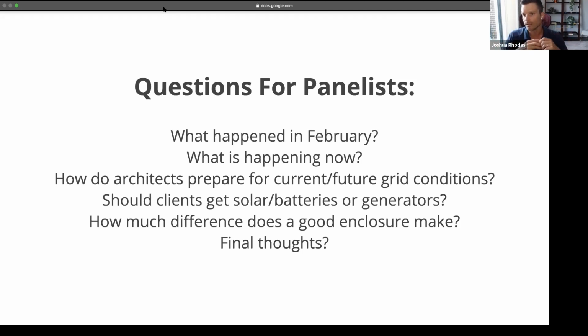At the same time, we lost close to half of our power plants for a variety of different reasons. As the weather event moved from the northwest down through Texas, we lost a lot of our wind facilities out there. We had a lot of icing up of our wind turbines. And then as the temperature moved along, we lost a lot of our thermal plants. Thermal plants have cooling water just like your car has a radiator, and a lot of those froze, and they were not able to keep the power plants cool, or they had sensor lines trip off, or a whole bunch of other things.